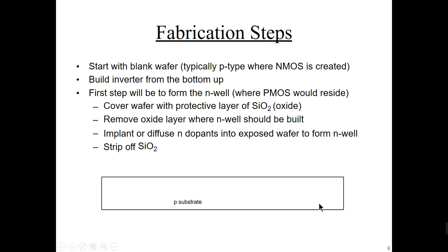And coming to the process of fabrication, now we can enter into the fabrication process. So the first step is selection of the substrate. Based on the type of the process we are using for the fabrication, the substrate will depend. If you are using the N-well process, definitely we have to consider the P substrate. Otherwise, if you are using the P-well process, definitely an N substrate has to be used. That is the base material for the designing of a transistor.